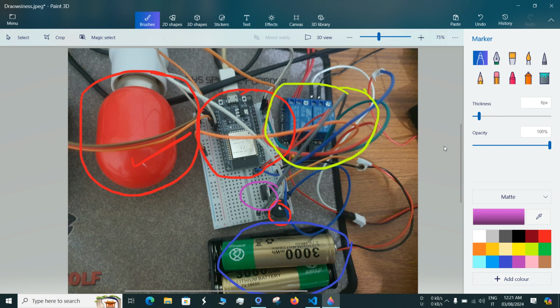And right now, with all this done, I would like to directly dive into the demonstration. Well, before that, one more thing: I have established communication between my computer and the ESP board using serial communication. That means there must be a wired connection between the computer and the ESP32 board. But if you want to, you can also transfer information from Python to ESP32 and vice versa by generating a local server on ESP32, and then by importing requests in Python, you can simply send any data to the server, and the ESP32 board can extract the data from the server and generate the control signal according to that.